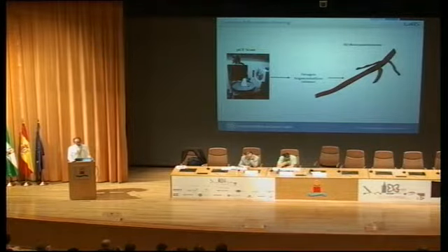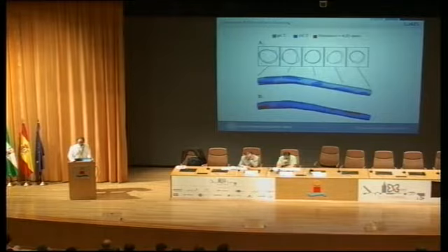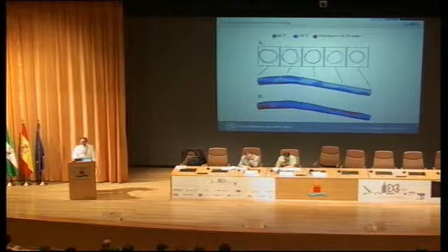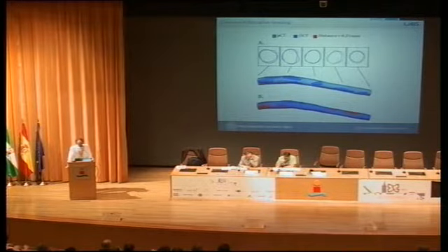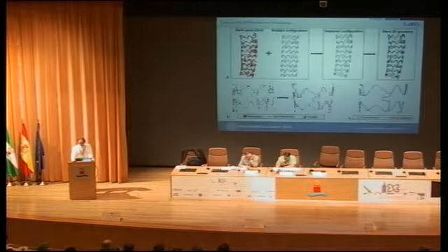In parallel, we ran a micro-CT scan of our sample, and with Mimics software we reconstructed our sample, and then we made a comparison of the two. There was some discrepancy in terms of the alignment, so on the twist angle, but the results were quite satisfactory. Keep in mind that the areas with a distance of more than 0.25 millimeters are those reported in red.